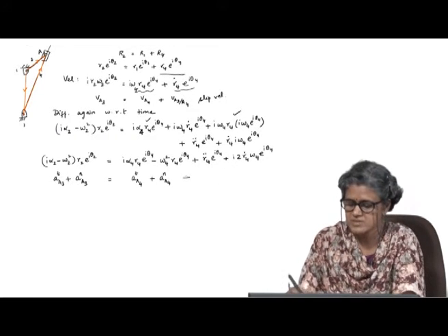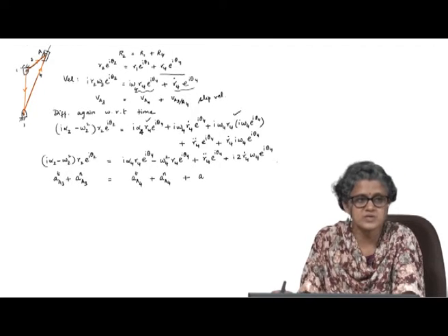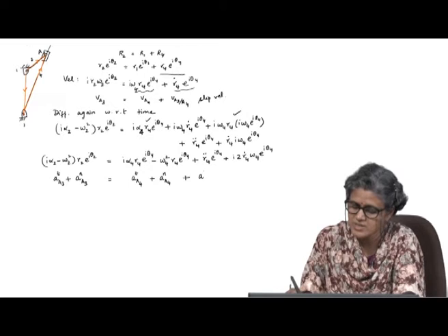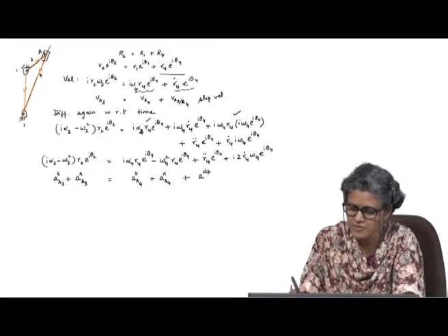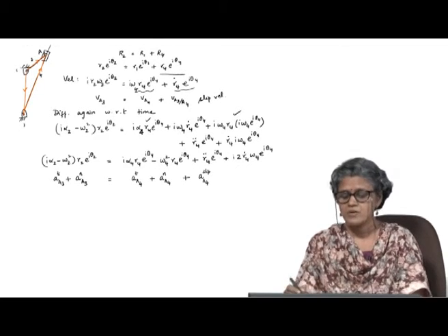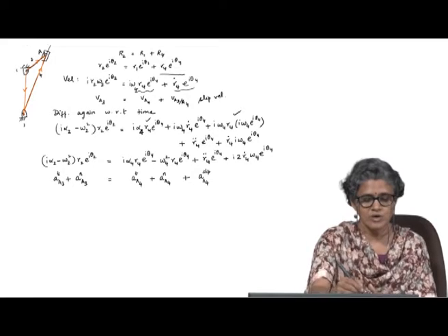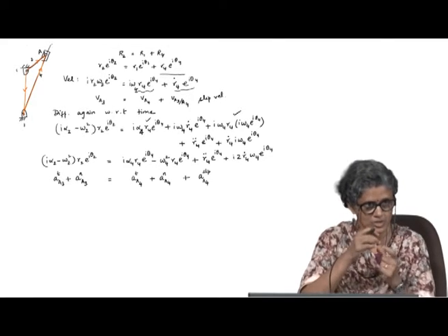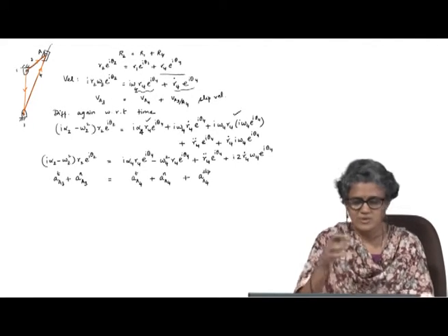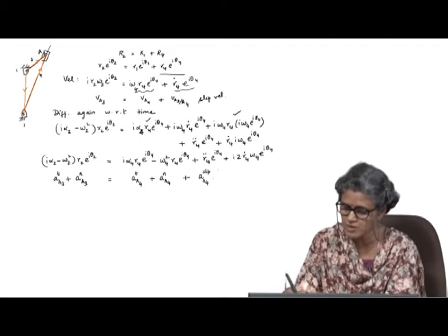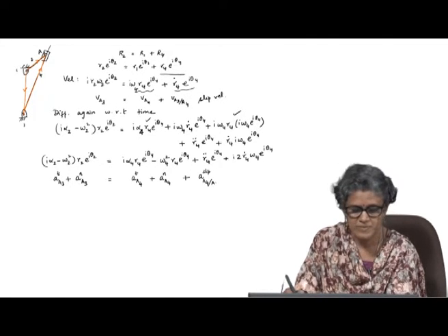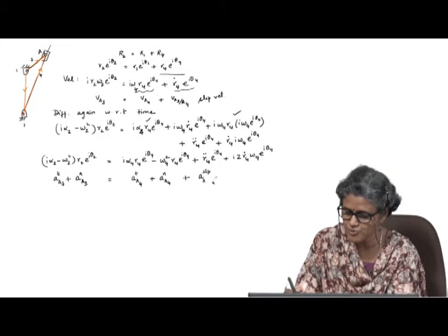Now, these two terms are something different. This is your slip acceleration of A on body 4. R4 double dot is along this, how the two points are moving, so it is the acceleration of A3 relative to A4.